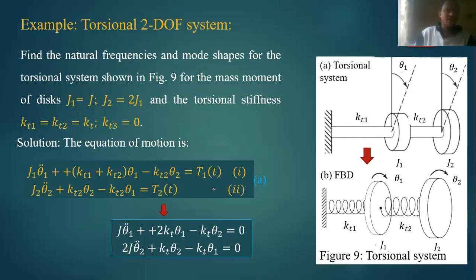To illustrate our discussion, let's take a simple example of a torsional system. Look, a shaft which is fixed here and which is having two flywheels here, and we have the shaft on this side with stiffness KT1, and the middle stiffness KT2, and the shaft is having θ1, the relative deflection, meaning the relative twist, and θ2 of the second shaft.